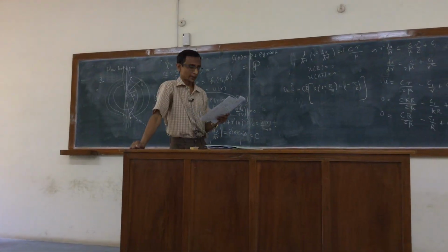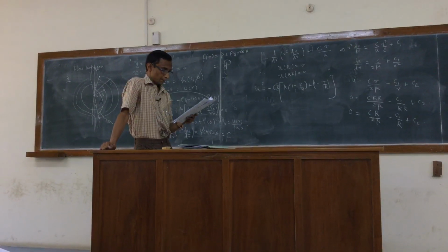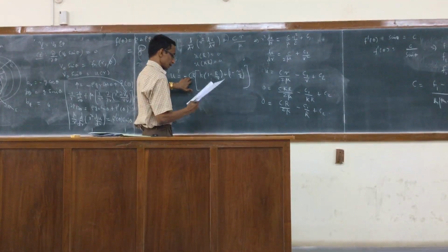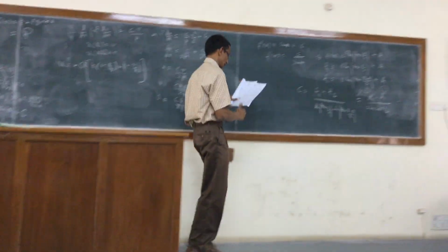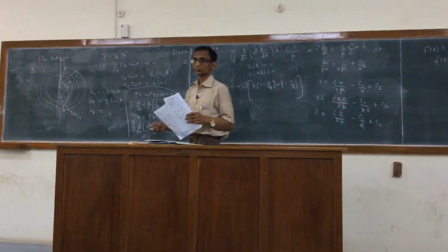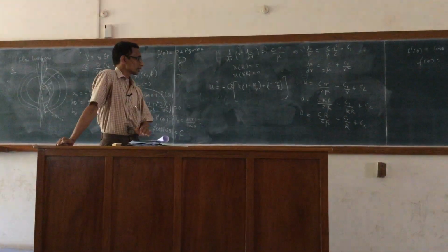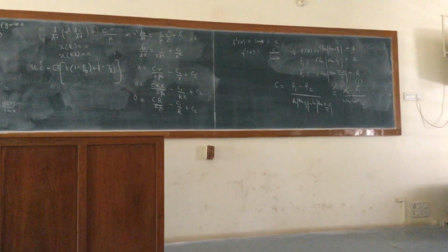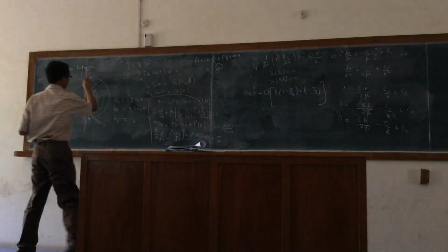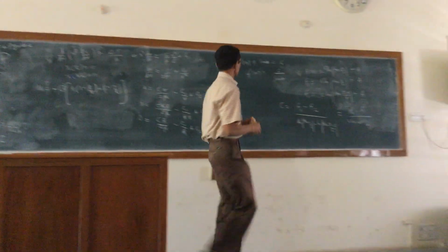This sort of completes the problem of calculating the velocity profile. The velocity profile is here expressed in terms of C, and that would have to be expressed now in terms of the pressure difference between the 2 points, right? So that is what we have, and then there's another question also here. Since there is fluid coming in, there is fluid flowing out, right? We also can calculate the mass flow rate, right?